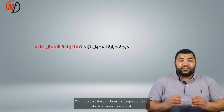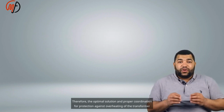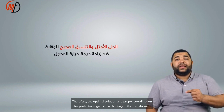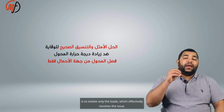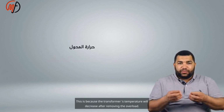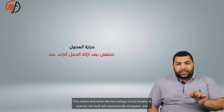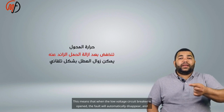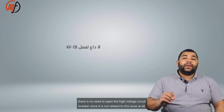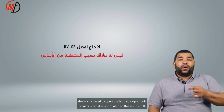This is because the transformer's temperature rises due to increased loads on it. Therefore, the optimal solution and proper coordination for protection against overheating of the transformer is to isolate only the loads, which effectively resolves the issue. This is because the transformer's temperature will decrease after removing the overload. This means that when the low voltage circuit breaker is opened, the fault will automatically disappear, and there is no need to open the high voltage circuit breaker since it is not related to this issue at all.